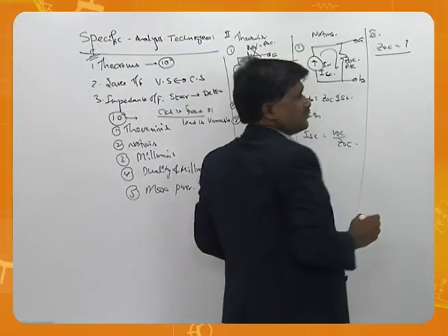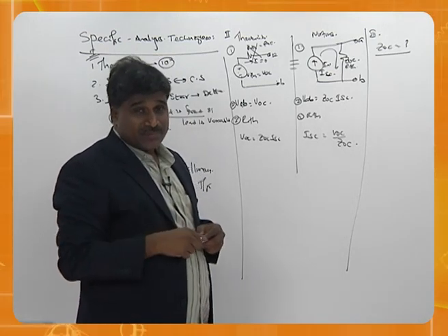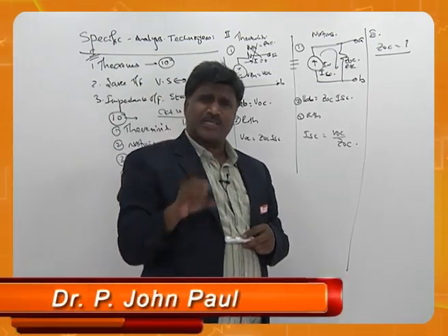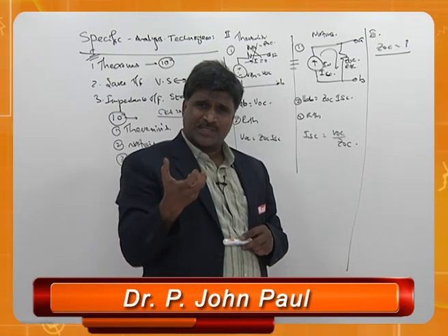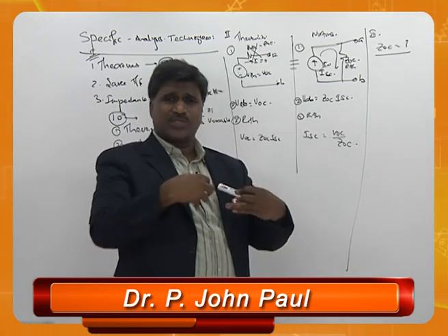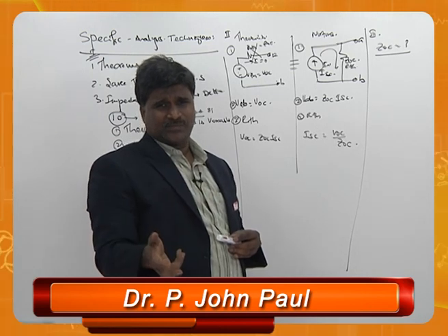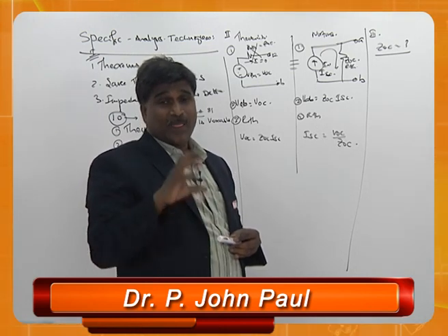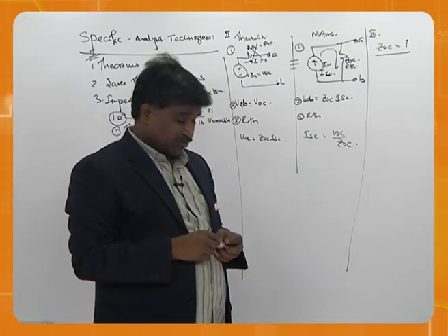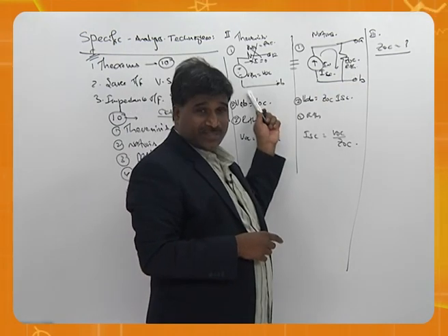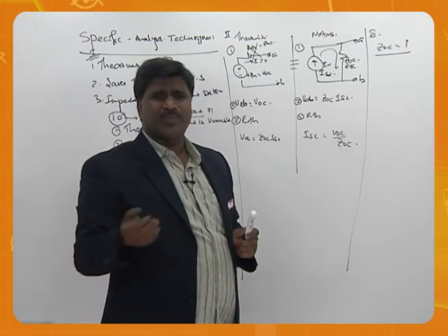That's the main idea, because that's common for both, and most of the time they are interested in impedance, particularly when you go to the maximum power transfer theorem. They need to know what is the impedance in order to suit that. When the impedances are equal, or the magnitudes of impedances are equal, maximum power is transferred. That's why ZOC became more important than VOC and ISC. Therefore, ZOC is required for Thevenin's, for Norton's, and even for maximum power.